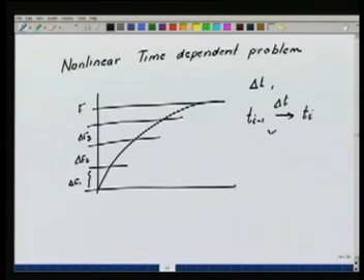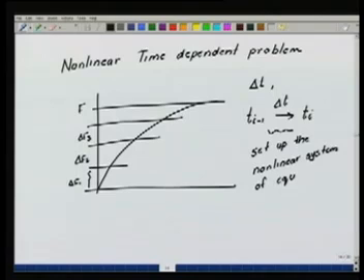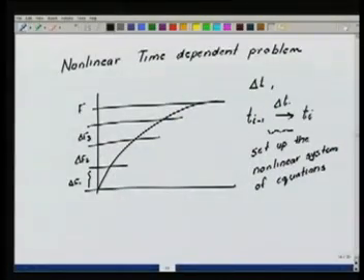Okay, then here I set up the nonlinear system of equations. Okay, and we can use the standard Newton-Raphson strategy that we have done, and we can solve this. So the good idea will be to break this into small steps. The time station is broken into small steps. For that time station, the load is broken into small steps. That is the amount by which the load increments.